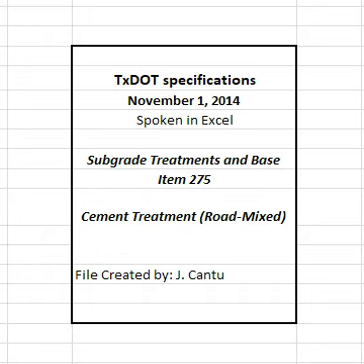Bags varying more than 5% from that weight may be rejected. The average weight of bags in any shipment, as determined by weighing 10 bags taken at random, must be at least the manufacturer's certified weight. Cement slurry will be measured by the ton, dry weight, of the cement used to prepare the slurry at the job site or from the minimum percent dry solids content of the slurry, multiplied by the weight of the slurry in tons delivered.